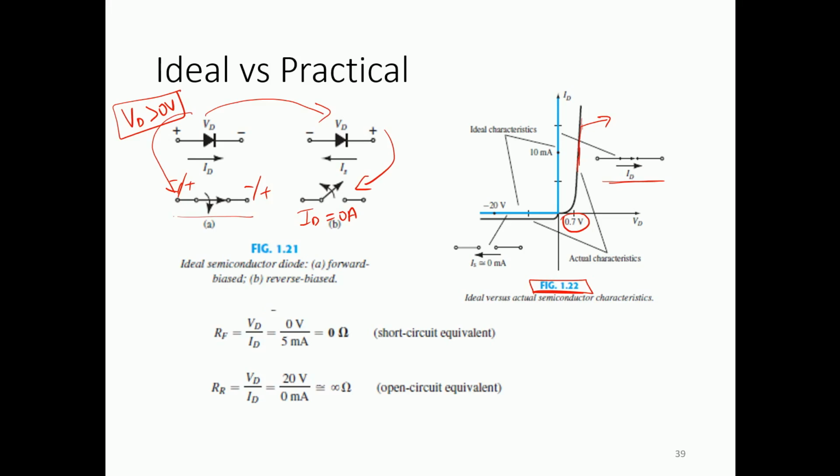Which means that in our upcoming analysis of the diodes involved in a circuit, for example, if I have a voltage source and a diode connected, and then we have a certain resistor, so this is my voltage source, this is the silicon diode, and there is some load resistor. If we apply a certain voltage, the current is going to flow over here. So in the coming analysis, we can replace this diode with its equivalent model, which can be a simple short circuit wire. So the structure can be something like this. So this is a short circuit wire.